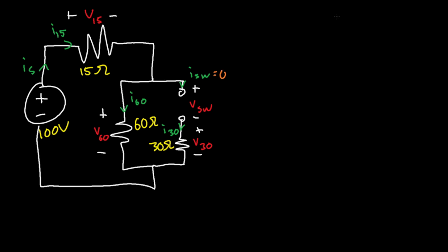So first thing we notice, easiest thing, the current. Bro, why am I writing volts? The current at the switch is 0 amps, right? Since the switch is open, the current is 0. All right, let's keep going on. Well, since this right here is 0, we'll notice that if we use Ohm's law, 0 amps times resistance, that means the voltage at this is also 0 volts.